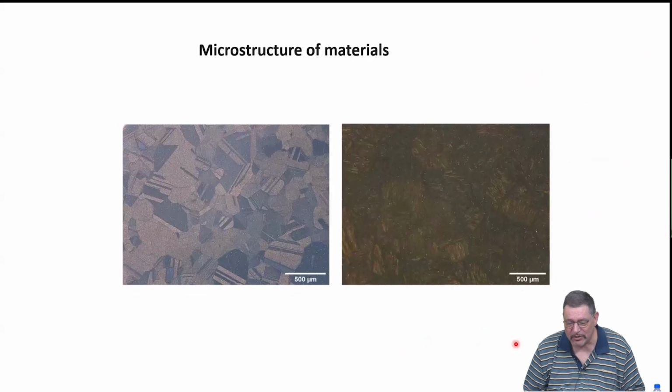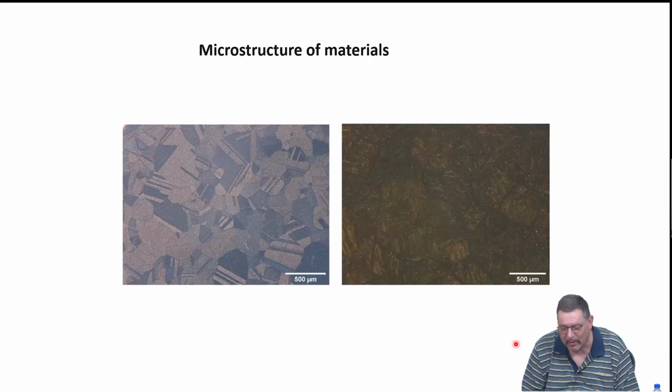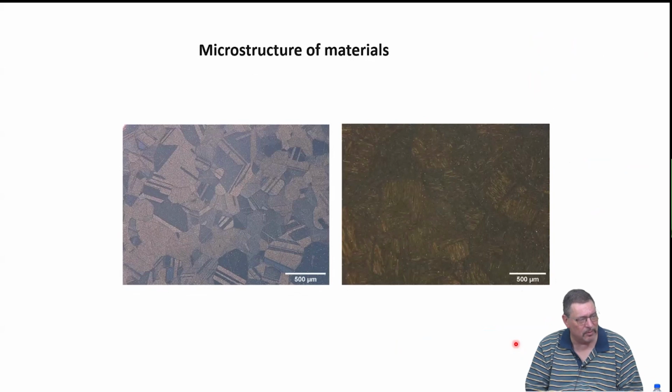So, microstructure of materials. I gather that all of you know about how to characterize, right? So you do optical microscopy or you do scanning electron microscopy, and you see different contrast arising from different optical properties, interactions, as well as different orientations. And I have to say, most of the high entropy systems have a microstructure that looks rather normal. So you have grains, grain boundaries. If you have two phases and you have a compositionally complex alloy, you have phase contrast, but there is not much more to it on this level.